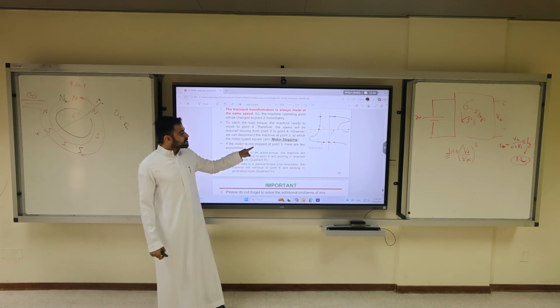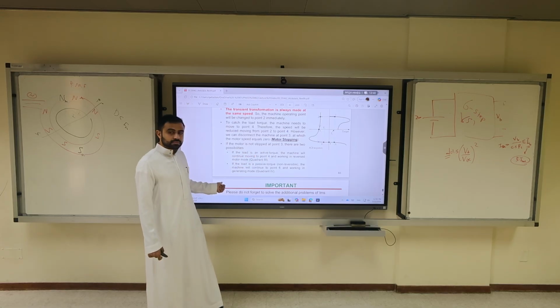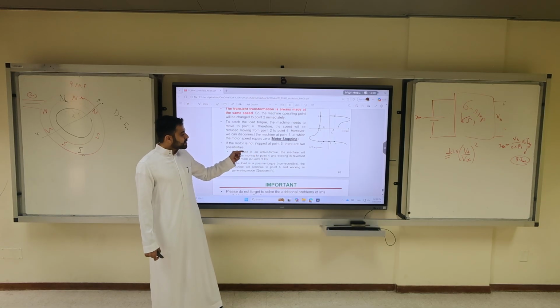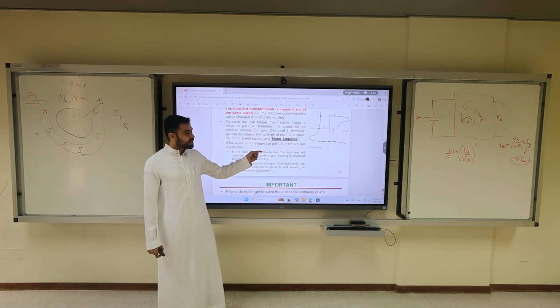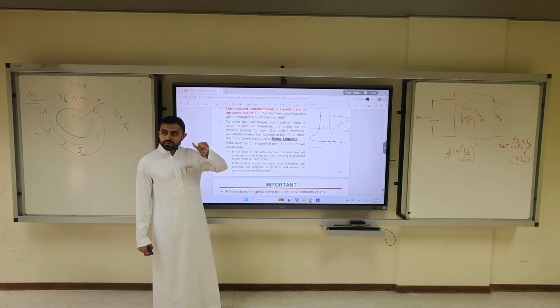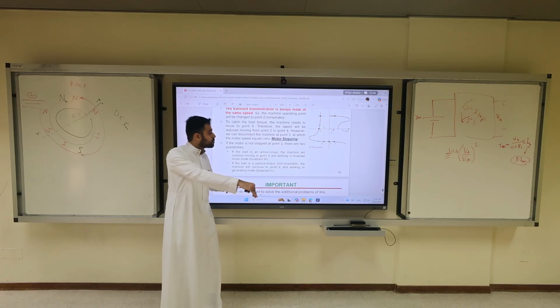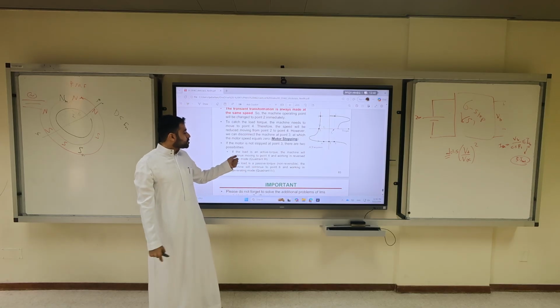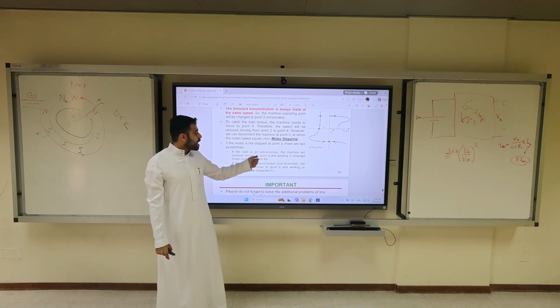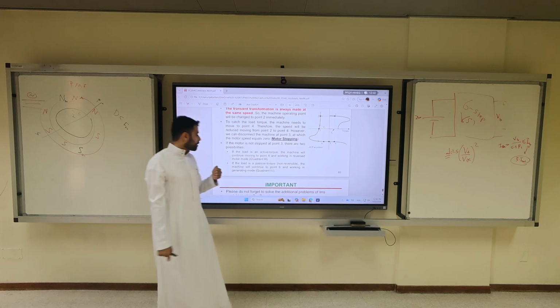If the motor is not stopped at point 3, there are 2 possibilities. If the load is active torque, what is active torque? It means it can reverse its load torque from counterclockwise to clockwise, similar to the car going up to the hill and down to the hill. The machine will continue moving to point 4 and working in what we call reversed motor mode or quadrant 3.